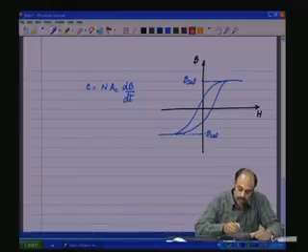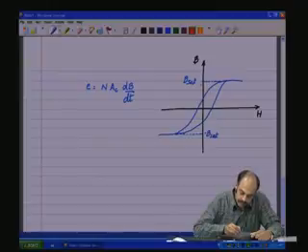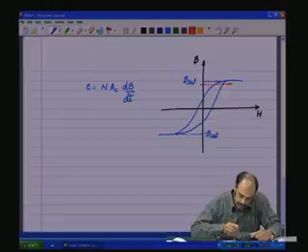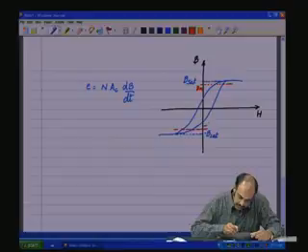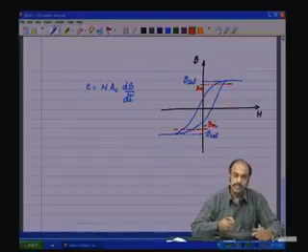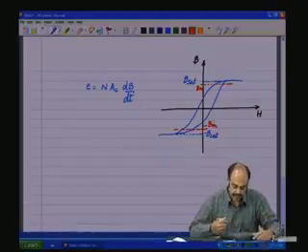So, you have to operate at a slightly safer value. Let us say that we do not allow for saturation and that the flux is allowed to swing only between some plus Bm to minus Bm, which is less than B sat.